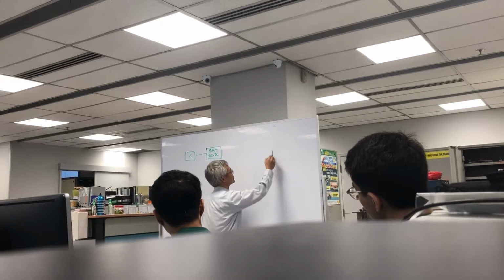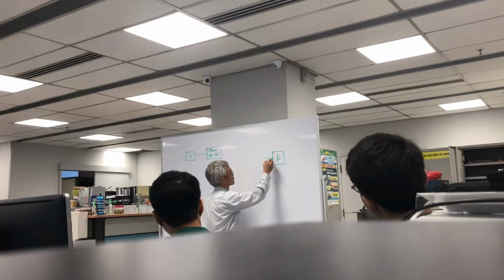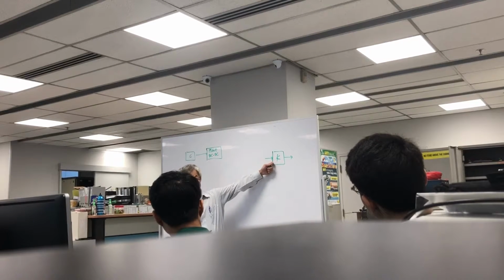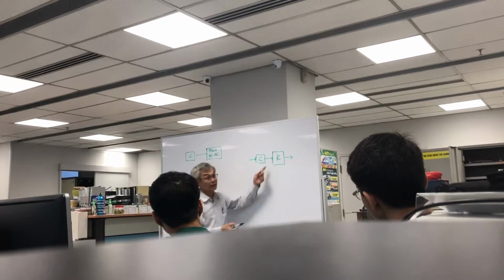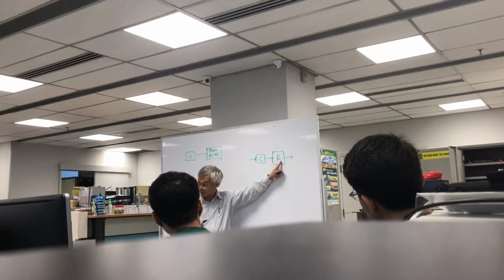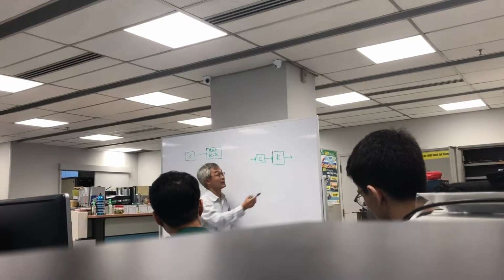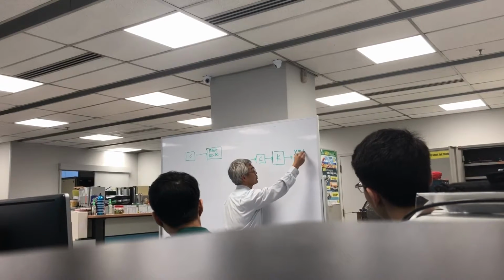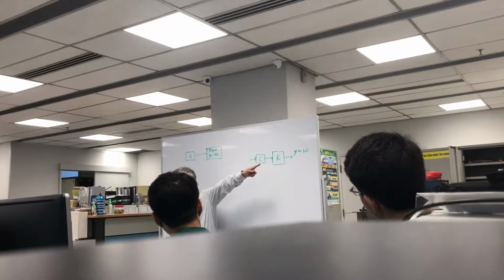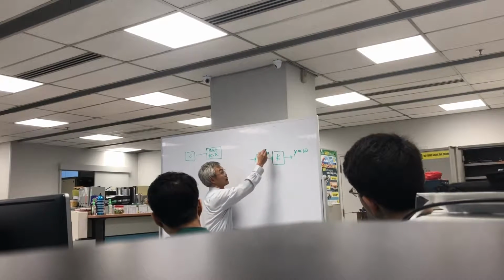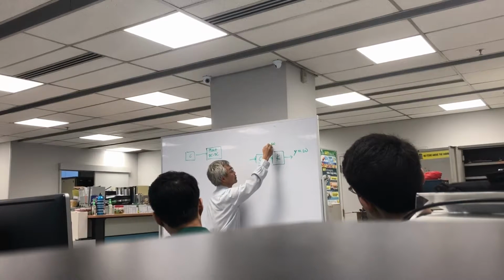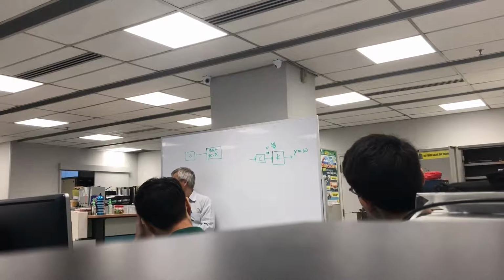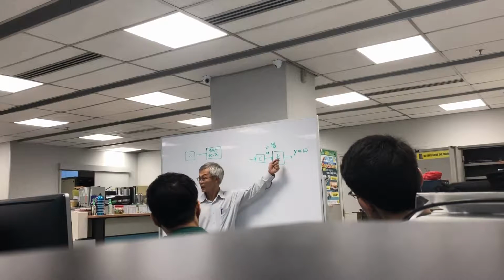A very simple thing is this. So this is a plant. Plant has a gain K. You have your controller. If you know exactly what this K is, this is your output. You want your output to be equal to your set point. What should you do with this? U equals W divided by K, correct? Okay, perfect. But the whole trouble is that you don't have perfect information.